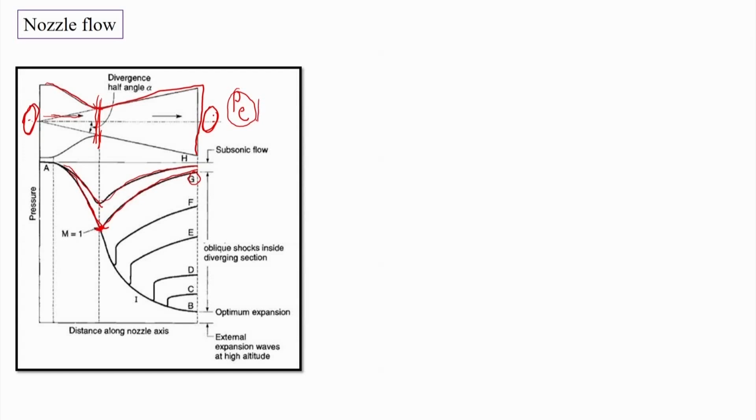If we decrease the pressure slightly below that critical pressure, the convergent portion still acts as a nozzle with no property changing in it, and a certain part of the divergent section will continue to act as a nozzle.